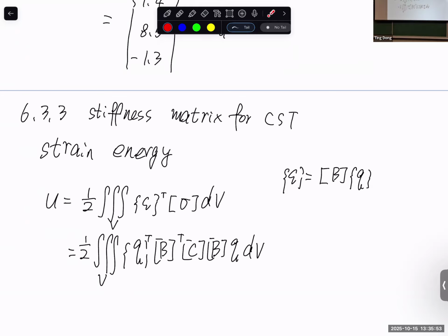Here I want to say that yes, we simplify as plane stress, but note that the simplification is based on the plate, where the stress in this direction is much higher than the stress in the thickness direction.